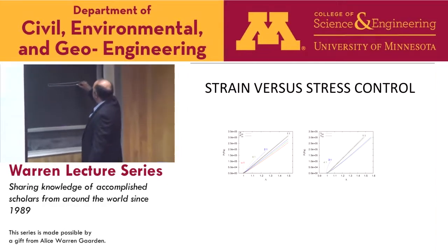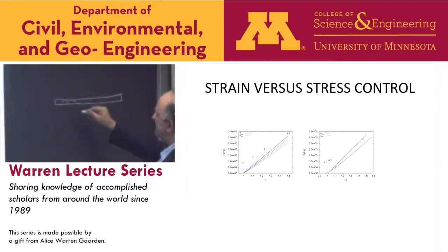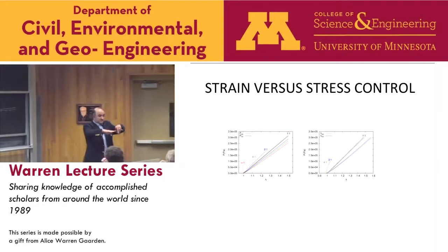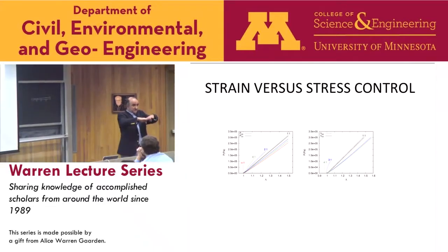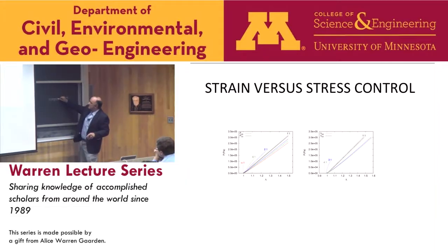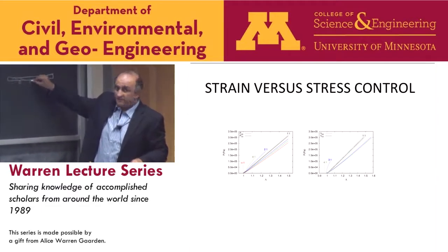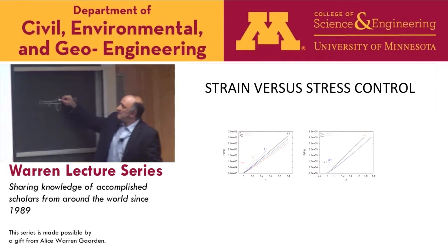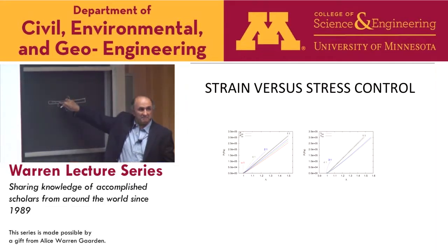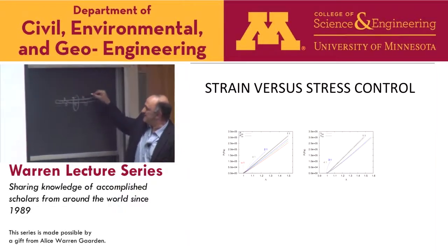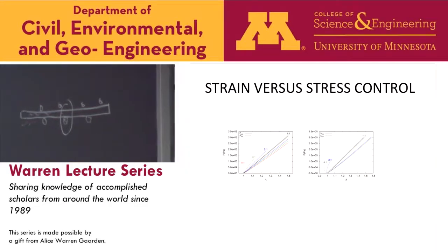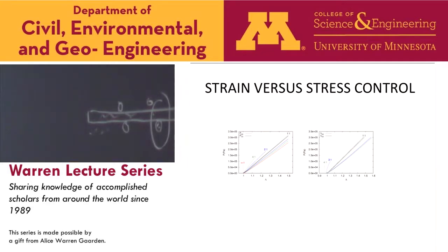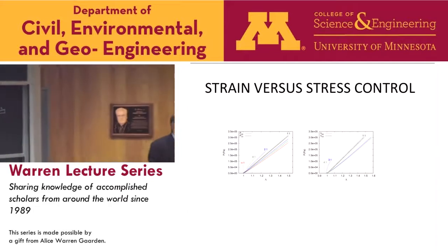So let's say there is a layer, all right, and there is this adjacent layer, right? And so the fibers have their diameters, right? And I put them next to each other, right? They're within the plane. And anytime there is a fiber from this layer, contacting a fiber from this layer, I denote it as a node, right? The intersection in the finite element business. And these nodes are no different from the nodes within the layer, right? So if you have, let's say, a layer in the middle, then roughly the number of contacts in such a layer will be 3 times more than the number of contacts in a single layer, all right? But there will be no fibers going in the perpendicular direction.